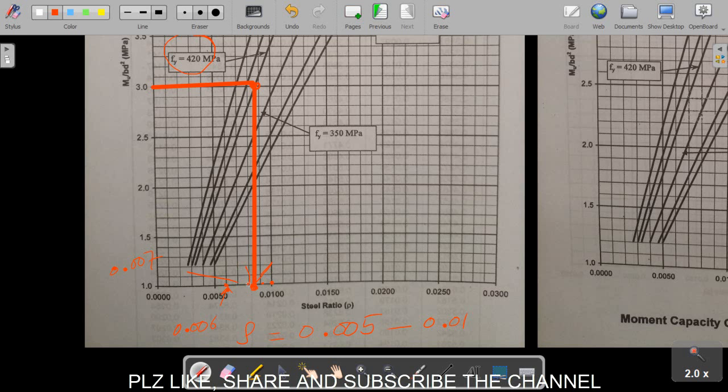So the value is in between 0.008 and 0.009. So we will use rho equals 0.0085, right? This will be my rho value, and the area of steel is calculated from rho times BD.